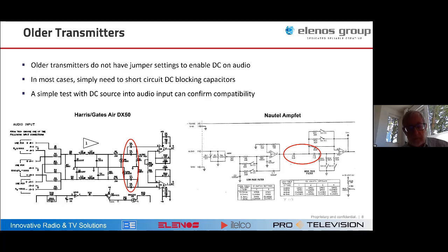And the other instance is we have one client, in fact, who operates MDCL on a transmitter to keep the antenna system voltage levels as low as possible because they've got an antenna system that for local political reasons can't be rebuilt and gives them voltage handling problems. And MDCL solved that very nicely.